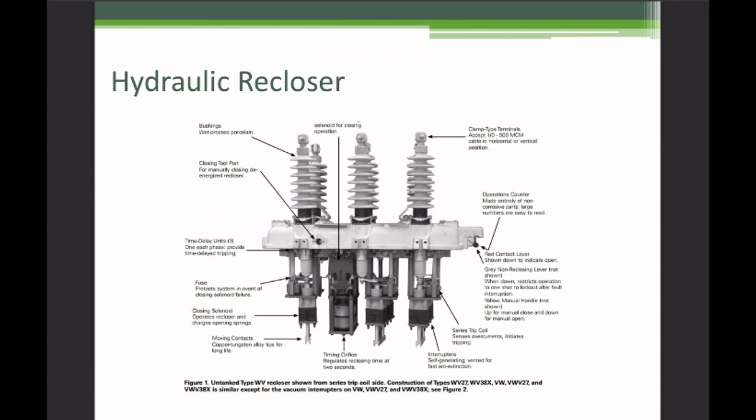Now, one of the other types of reclosers that you will almost certainly see in your career is the hydraulic recloser. These are an old style that's been in service for many, many years, well before the advent of computerization. And they are a shunt device. So the line is coming in, there's a bushing, and it goes down into the recloser, and there's another bushing, and it comes out from the recloser, and internally it actually feeds right through.